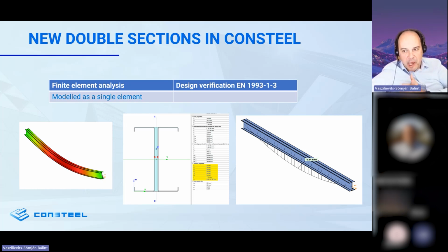If the displacement is not cancelled by continuous connectors along the length, but the connectors just have a certain spacing, then between the spacing the profiles can move a bit. Therefore, this bending, which is caused by the shift of the effective cross-section, can in reality be realized, and therefore this additional bending moment can also appear.